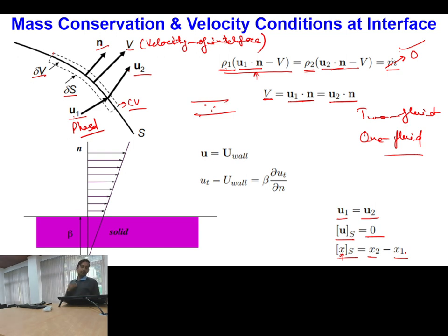So how to account for these partial values, that is something defined for a solid wall. You can consider this is a solid wall, and say I am operating in the range of a few hundreds of nanometers. In this scenario, molecular effects will also come into the picture. So I will not have a velocity of the surface purely at rest, because at this point the continuum is not fully satisfied. That's why we will find that the velocity of the fluid at this point has some magnitude. But how to define velocity at this wall?